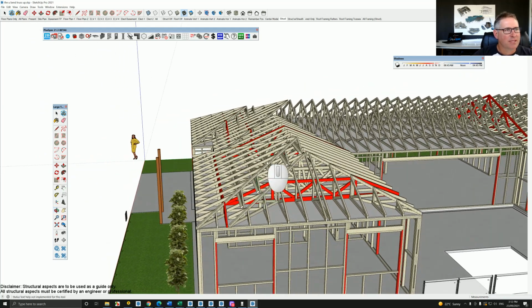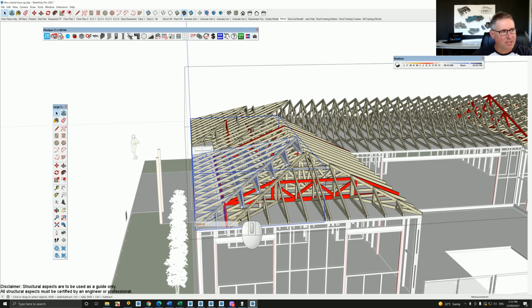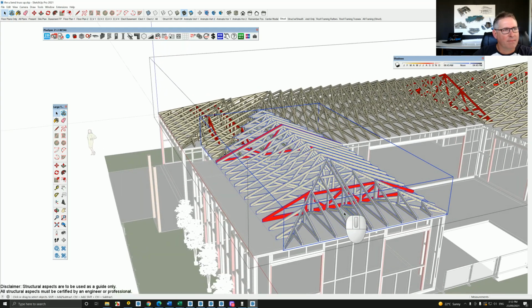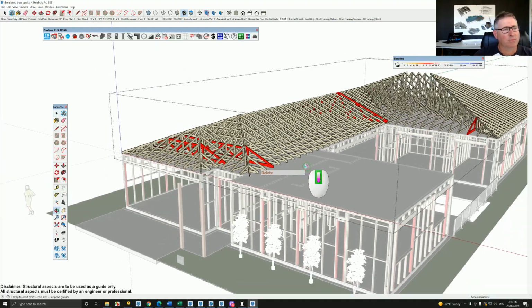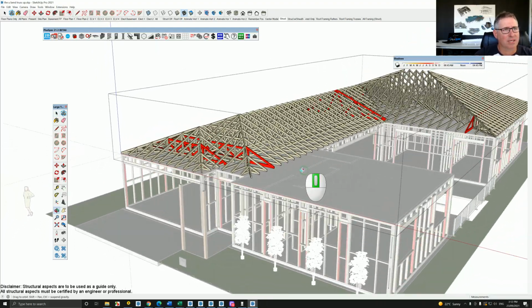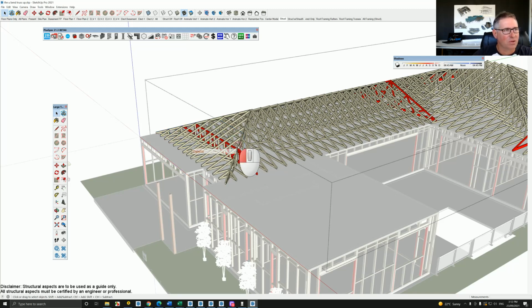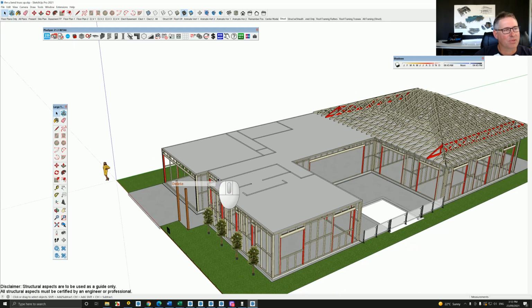Okay, so basically when these trusses here were drawn, they've been done as a valley, which is well thought out, however not quite right. So really these trusses here should have actually started from here and run back. And look, even though I'm not sure if this is design intent, I'm going to do what I would do in this particular instance. Is I'm going to actually get rid of anything that would be a problem and square up the front of the house. I would suggest probably different ways of giving the house a little bit of depth.